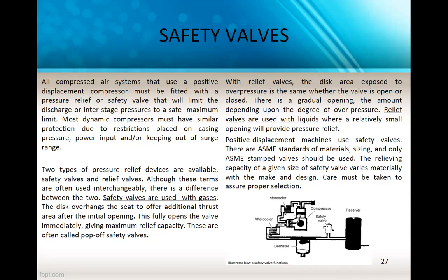Although these terms are often used interchangeably, there is a difference between the two. Safety valves are used with gases. Relief valves are normally used with liquids. The disc overhangs the seat to open additional flow area after the initial opening. This fully opens the valve immediately, giving maximum relief capacity.